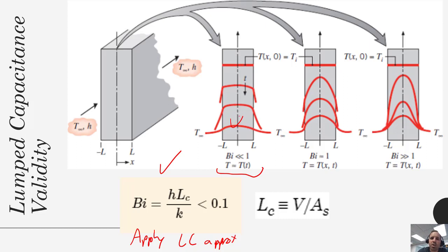But you can see as you go along in that cooling process, the system with the low Biot number, the temperature profile throughout remains pretty flat. Whereas on the far right extreme, as this process starts to cool, think of this as kind of like the oak wall. And this is like the steel wall, only we are cooling instead of heating in this particular case. But notice that the oak wall still maintains these really deep temperature profiles. So the lumped capacitance approximation would not be quite as good here.